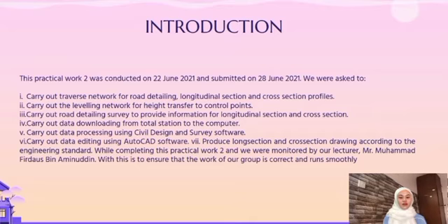Carry out the leveling network for height transfer to control point. Carry out road detailing survey to provide information for longitudinal sections and cross section. Carry out data downloading from total station to the computer. Carry out data processing using civil design and survey software. Carry out data editing using AutoCAD software.